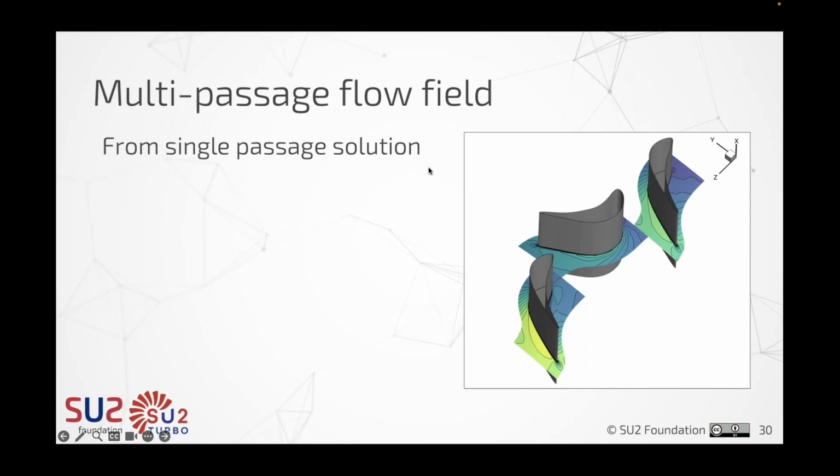However, we might want to see the solution for several blades. That's first of all very important, I think, to read more easily the flow field, and also if you want to make sure that your calculation is really periodic along these periodic lines, I think it's much better to have several domains or several flow passages.